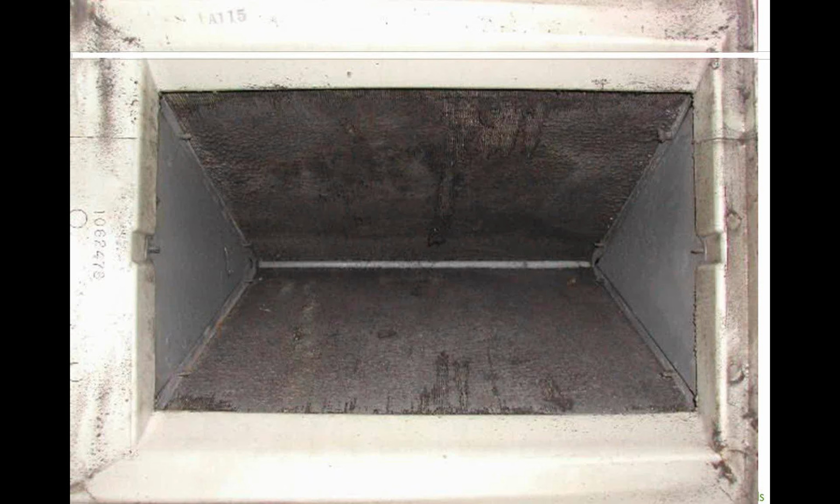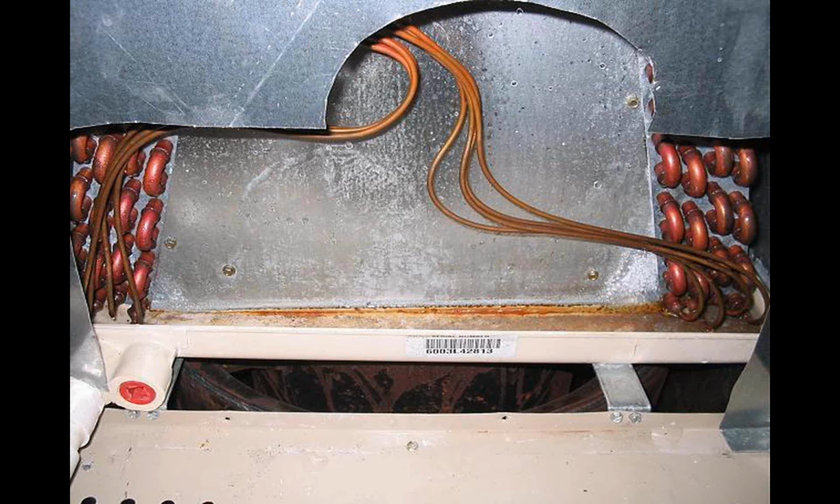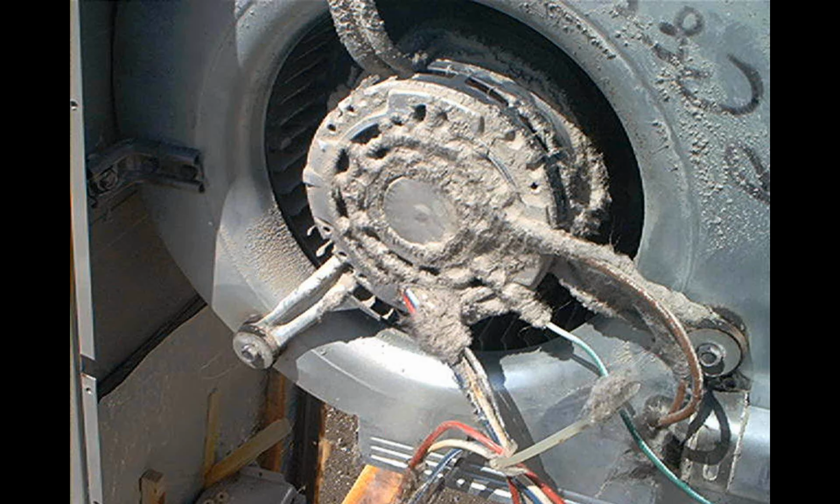Things like a plugged evaporator coil, obviously the system cannot operate at its optimal efficiency. Air bypassing a coil, we're going to have problems with efficiency. Or just a simply dirty blower wheel. A 1/16 of an inch of dirt on a blower wheel can degrade the efficiency, I believe, up to 60%. So there's all kinds of things in this industry that we need to make sure we're looking at, and dirt's probably the biggest culprit we have out there.